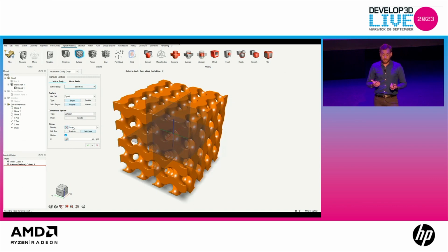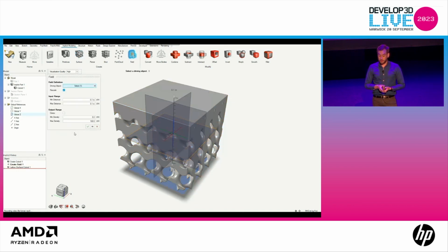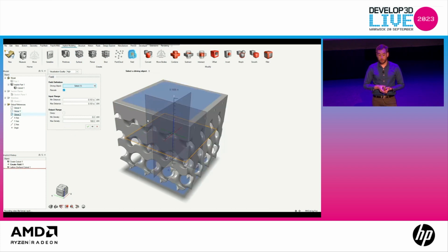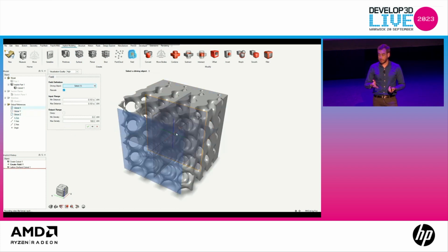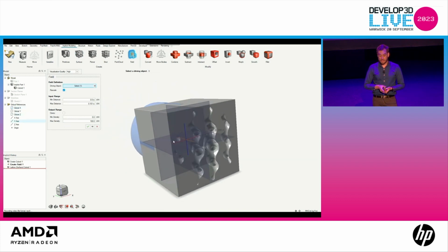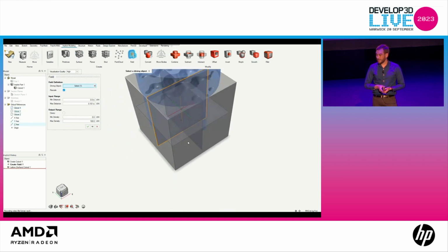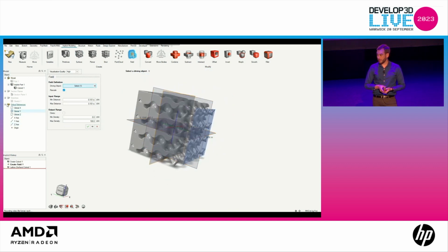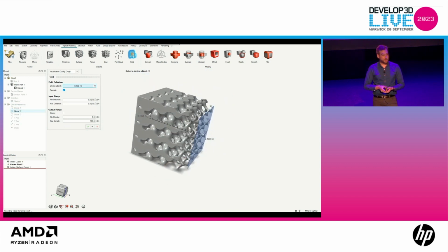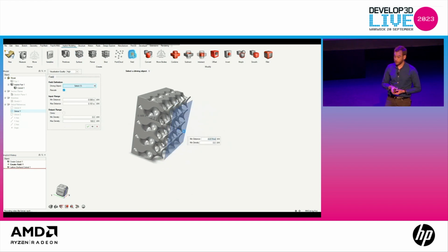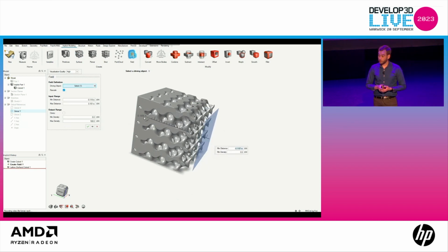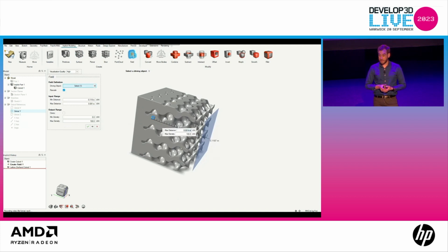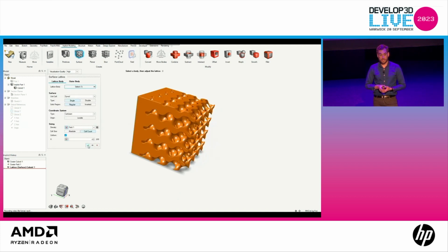Well, we can apply a field to the lattice, and we can choose either one of the global planes in the browser. We can click any plane in the viewport, and you can immediately see it change the field that you see on screen. So you can have radial gradients, you can have linear gradients, you can have spherical gradients, gradients off of all sorts of geometries, which you can then manipulate and visualize immediately as you move all of the widgets around.